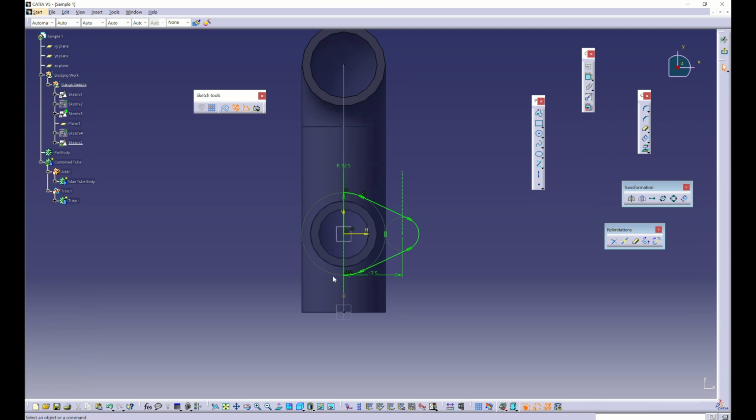So we're just cutting the circle here. Then next is click these remaining solid lines, and we are going to mirror this one. Click the mirror and click the reference, this V directional axis. Then voila.